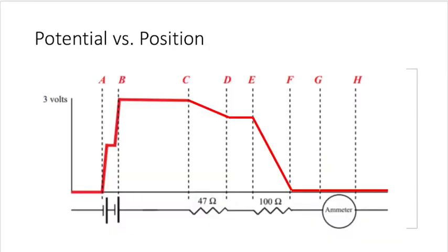The voltmeter was used to measure the potential difference for each part of the path around the circuit. This was done by touching the two leads of the voltmeter to the two points measured. As you can see by the graph, the parts around the circuit summed to 0, holding true to the loop law. There are both positive and negative potential values around the circuit, eventually canceling out.